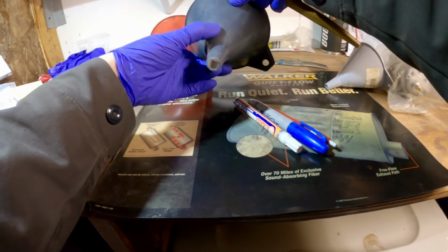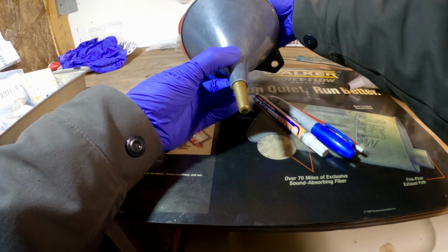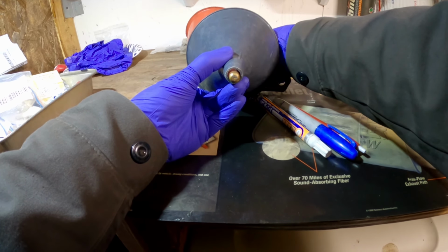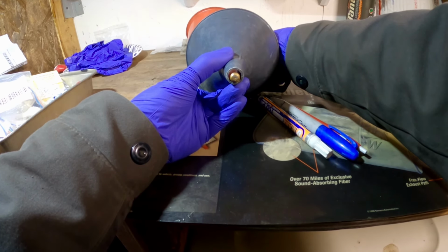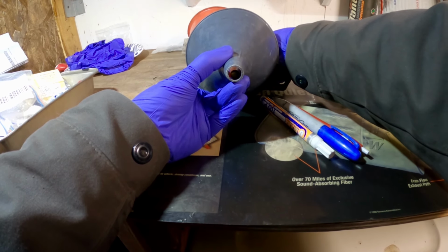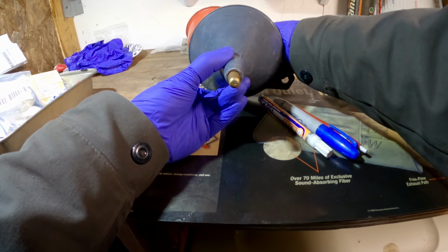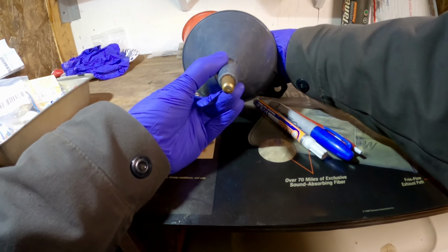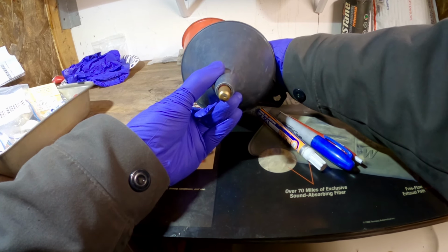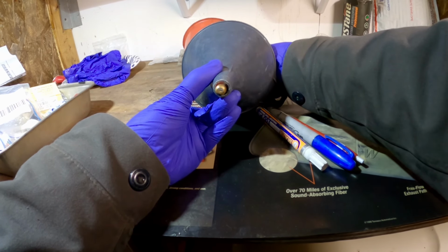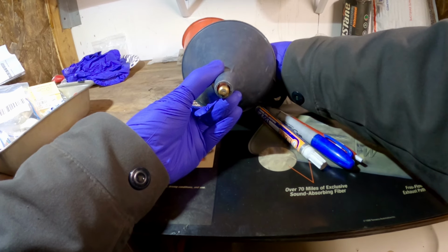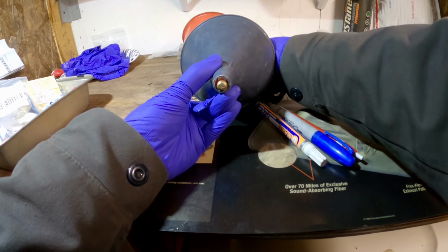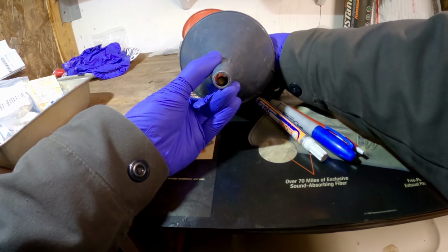Or maybe I'll move to this gray one, and we can see it totally blocked off. And look at the area. It's getting larger, infinitely variable almost. Look at that, until this comes out, and then we come back down and it blocks off, and there's a tiny bit of area. So there'd be a tiny bit of flow. When I pull this out farther, look at the area, the effective area gets bigger. Therefore, you get more flow through it, whether a liquid, an air, or a fuel. In this case, we're looking at slide carbs.